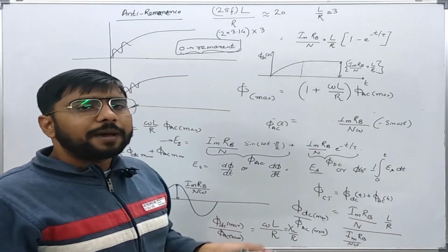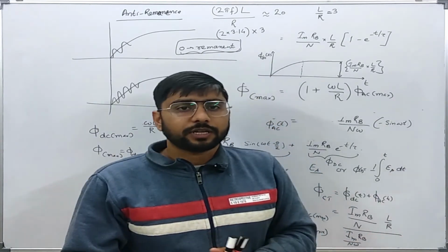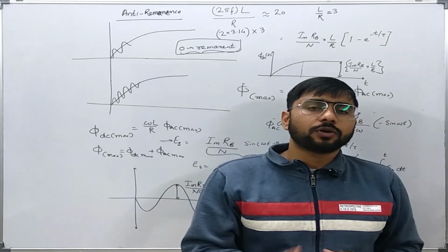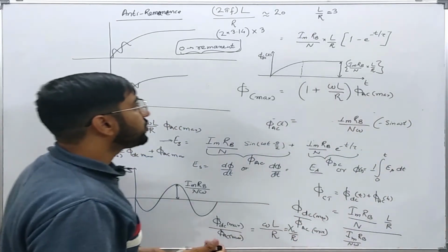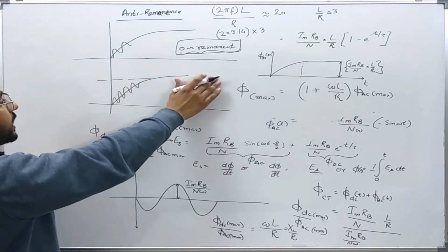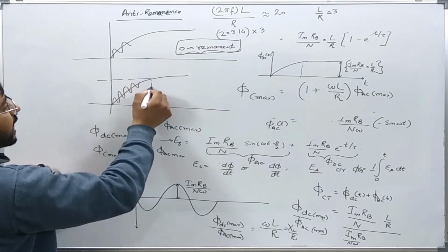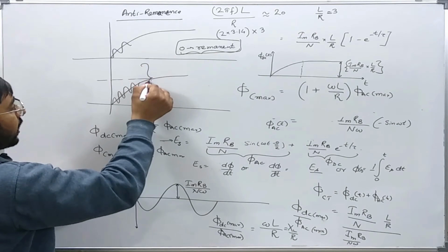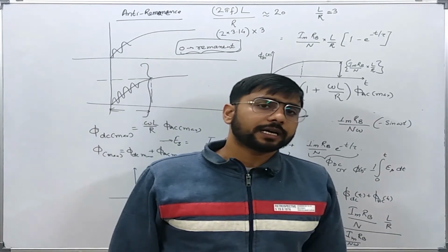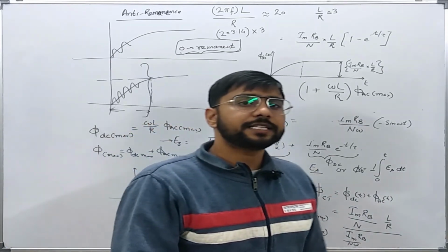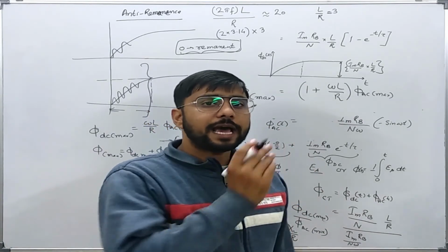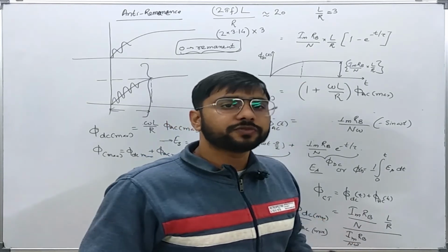But usually the relays which are required to act, act very fast. They act within just one or two cycles of the initiation of the fault. So initially this flux is not going into saturation. This flux also takes some time to go into saturation. So if our relays are fast enough to act within this time, before saturation occurs, then we do not need any special design of the CT. So a fast response relay will help us avoid the specialized construction of the CT.